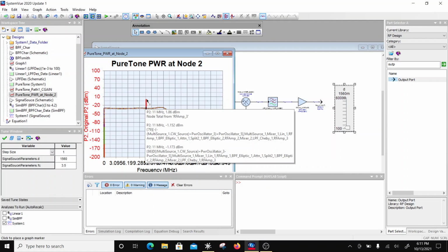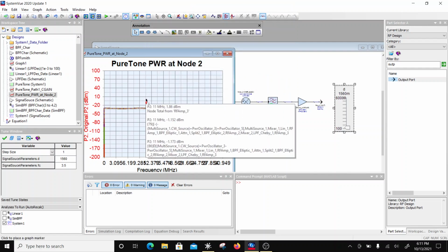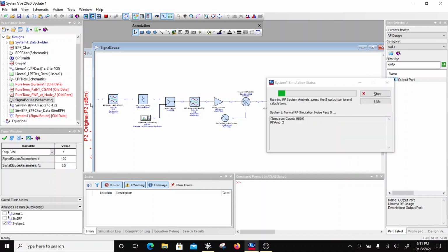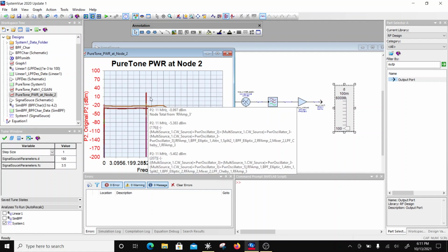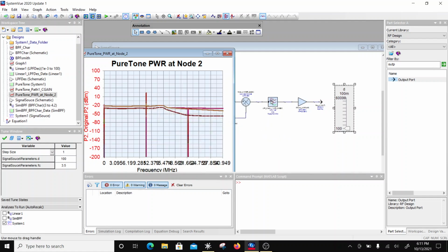And at 1.5 kilometers, okay, this power level has gone up to 1.8 dBm, right? And this one is minus 30, so we are well above the signal to noise ratio of the detector. But here it is minus 1. It is around 1.8 dBm. So basically, if I go further down to 100 meters, I am at 25 dBm.